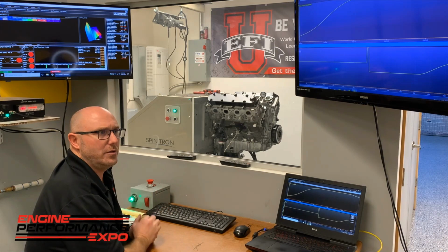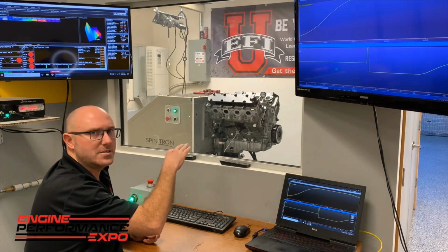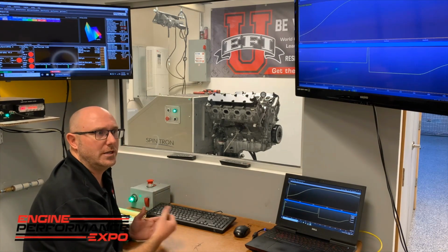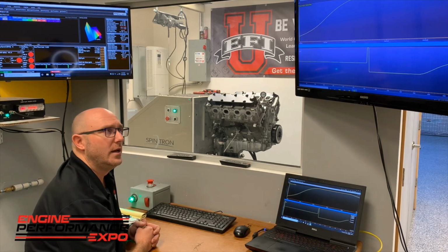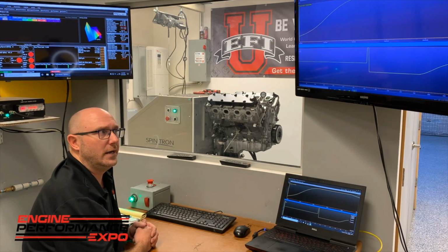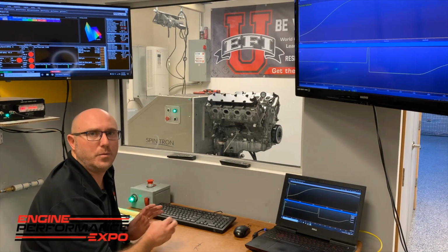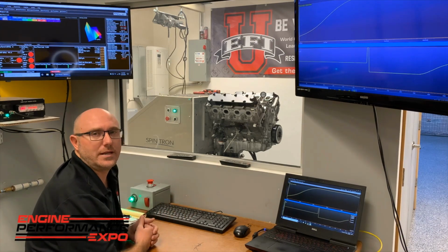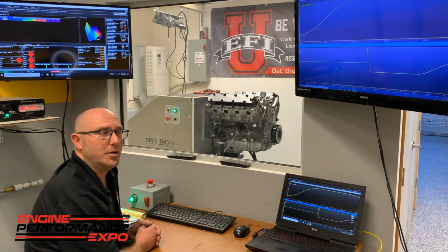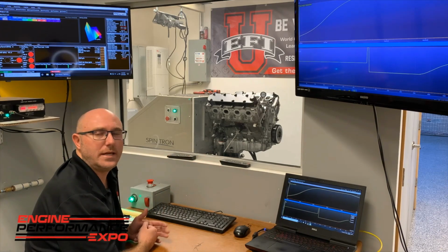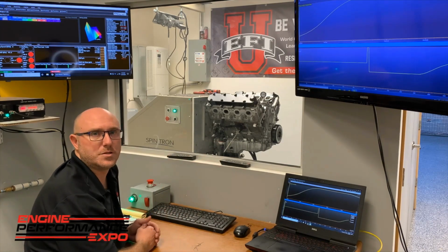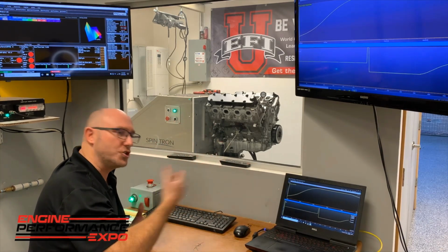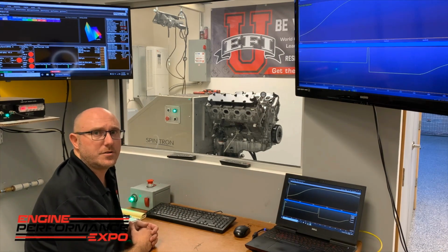And we typically will do this kind of like a dyno pull, where we'll start out slow, and then we'll ramp up. And that's what I'm going to do for you today. But we can also do racetrack simulations with gear shifts and throttle lifts and whatever else we want, as we sometimes find that there are advantages to paying attention to the finer points, the stability of the valvetrain to recover during a very fast negative transient, say like a gear shift, where you might be at 8,000 RPM and 0.2 of a second later you're at 5,000 RPM. So that jerking of the crankshaft, timing chain, timing belt, all that stuff being jerked back the wrong direction sometimes can upset the valvetrain. So we look for that kind of stuff.